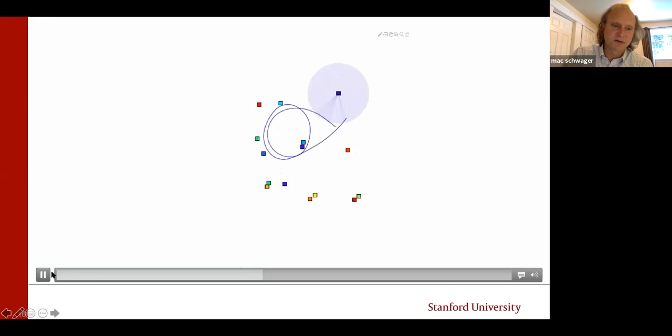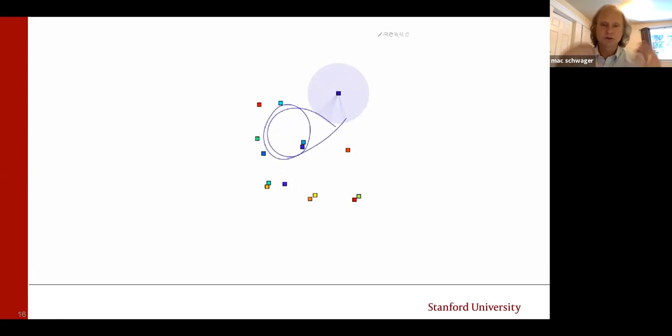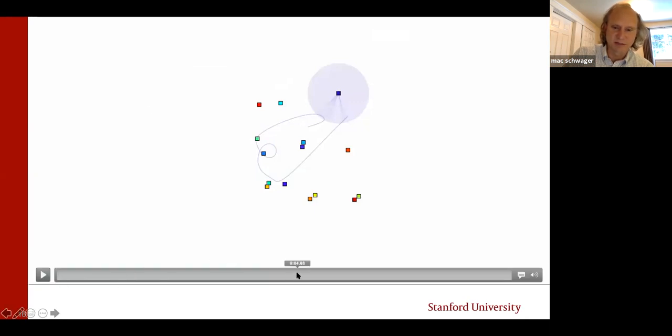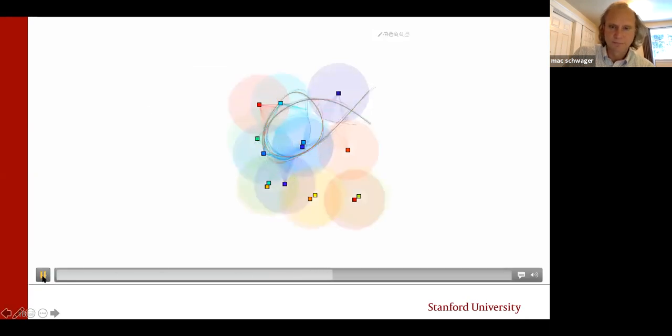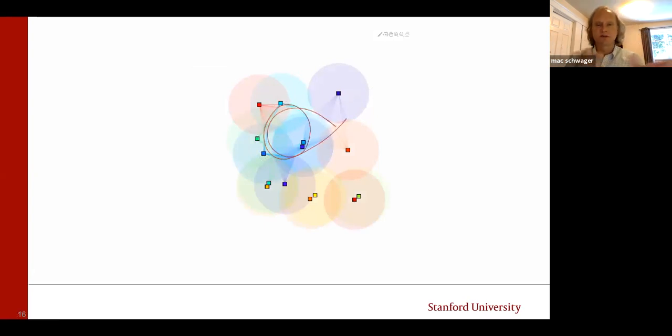So you can see how that trajectory estimate relaxes through iterations of the optimization. And now I'll show you, superimposed, this same perspective from all of the autonomous cars that are at the same time estimating this quantity. You can see the trajectories that they believe are correct start off quite different, and then they converge and relax to one common trajectory that's shared by everybody asymptotically. And this is the maximum a posteriori trajectory given all the data in the whole network. Okay, so this is visually how it's working.